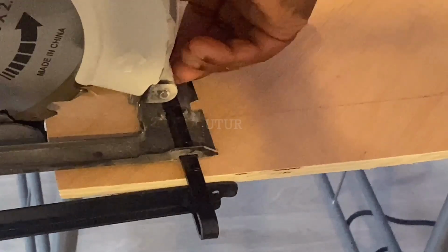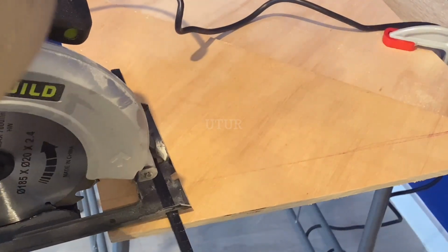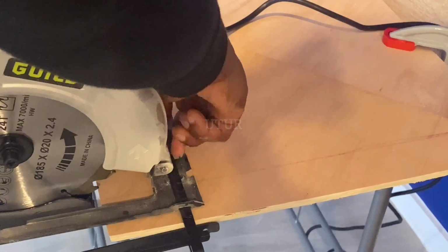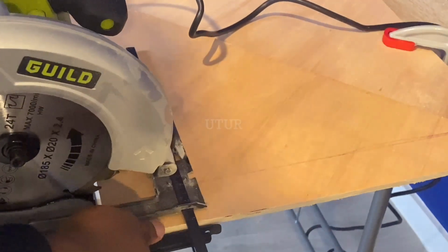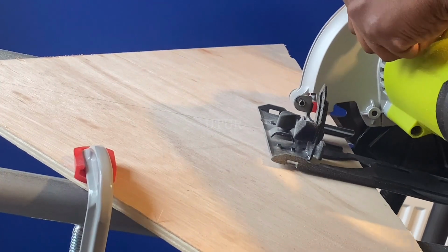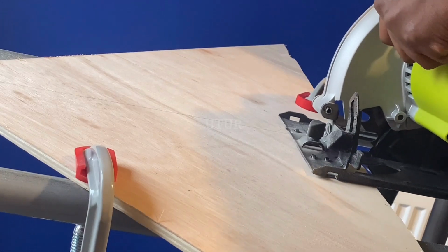Okay, and for a simulation of how the blade impacts or cuts through the plywood, let's revert back to the initial highlights of making diagonal cuts with the circular saw. The only difference is that in this case we've just included or retrofitted the rip fence or the parallel guide to enable us to make accurate cuts, as opposed to just doing it freehand with the cutting line. And this is what I mean here, freehand in relation to the cutting line when you're making diagonal cuts.